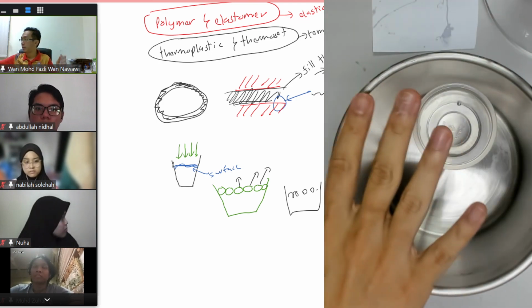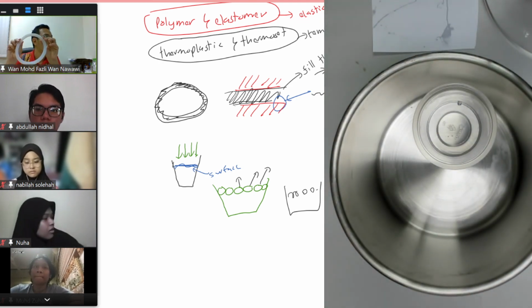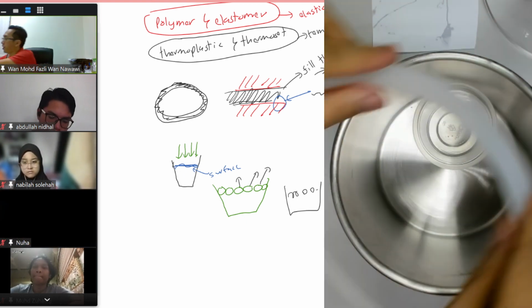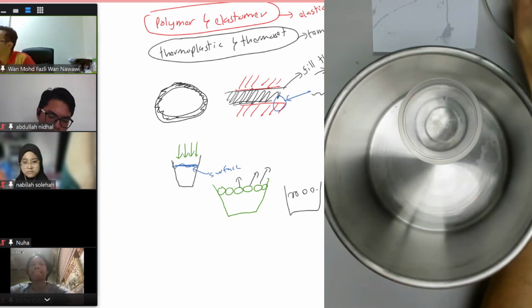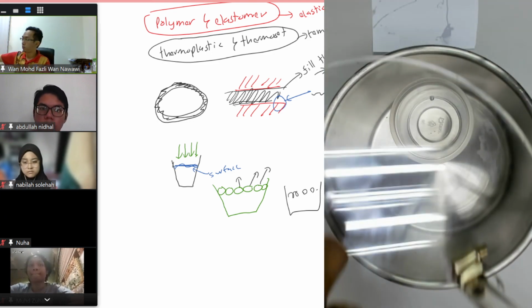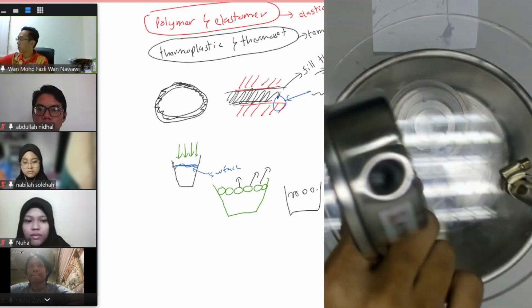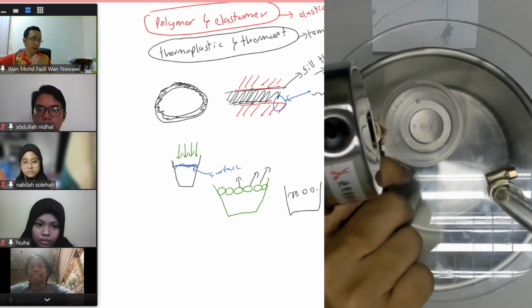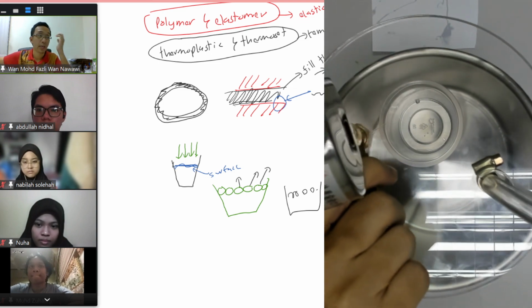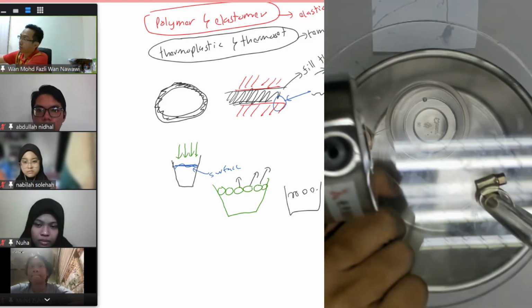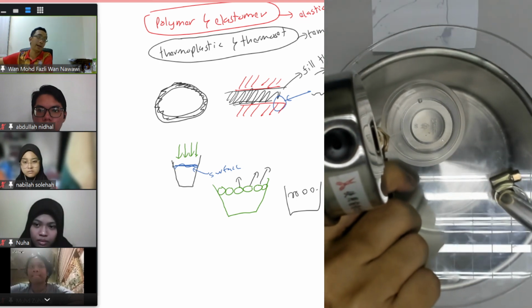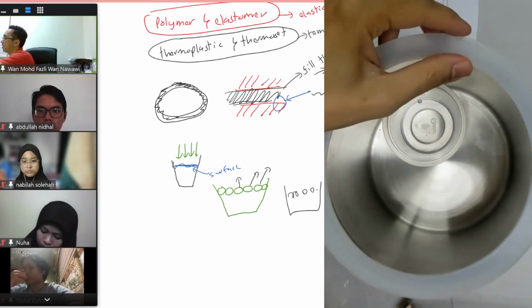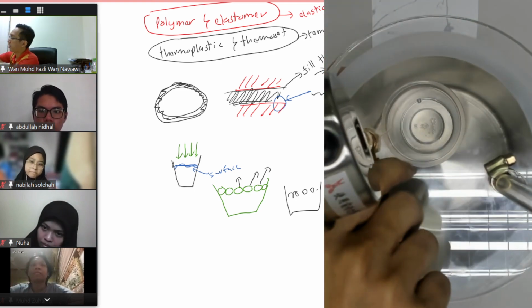In order to close this thing, you need a gasket. So this is a type of gasket, made from silicone. So you put it there, because this top is just acrylic plastic. If I put it like this and bring the air out, it will not create a tight seal. That's why I need to use this gasket, this elastomer, and then you put this thing on top.